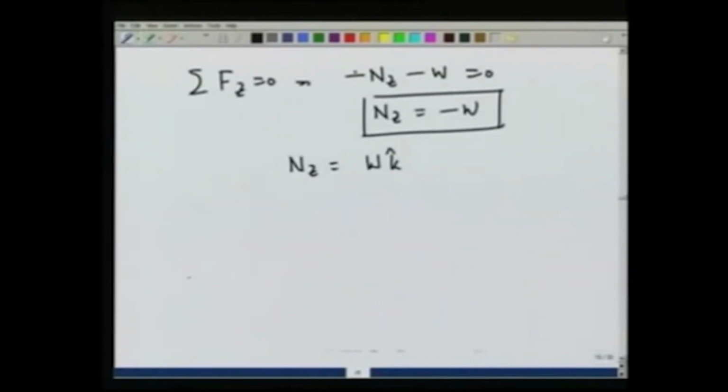So, what we have determined on this rod or on the pole that has been put in a ball and socket joint is that there is a force on this due to the ground, due to the hole on the ground, which is equal to 2 T cosine of alpha.